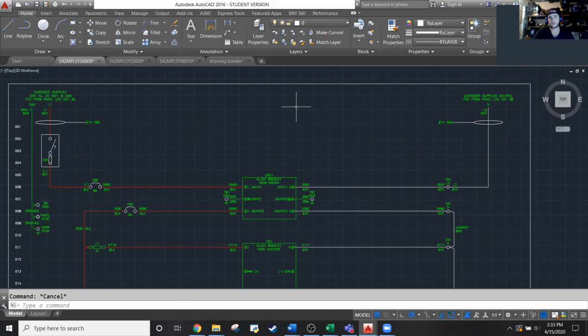What we're going to be looking at is how to do drawing sets for a PLC control panel. The first thing that's going to cover is just simple power distribution for the 120 AC coming in. It's going to go to a power supply that transforms that 120 AC into 24 volt DC, and then distributes it to all your 24 volt modules. There's also going to be a decent number of modules in there that take 120 AC.